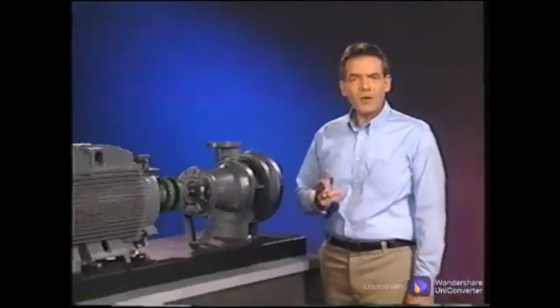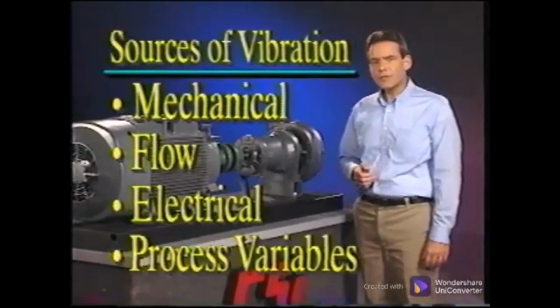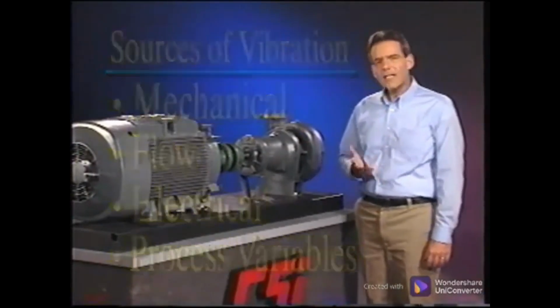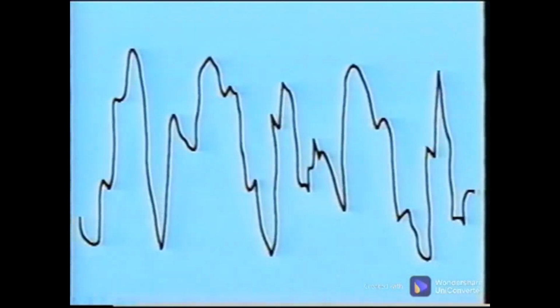It is important to understand that there is a mechanical or electrical occurrence represented by every peak in the spectrum. The source of the mechanical vibration could be flow, electrical, or some other force, but the effect we measure is mechanical vibration. If this data was from a pump, a peak could show up which would equal the number of vanes on the impeller. The waveform here is more complex because of the added energy. Now during one rotation of the shaft, 7 complete cycles are generated.